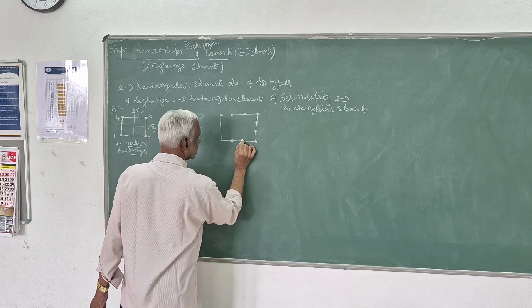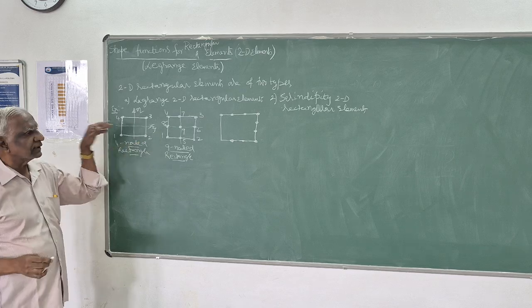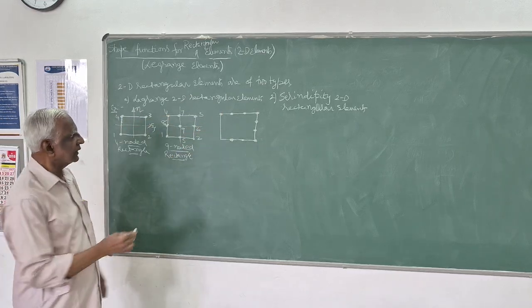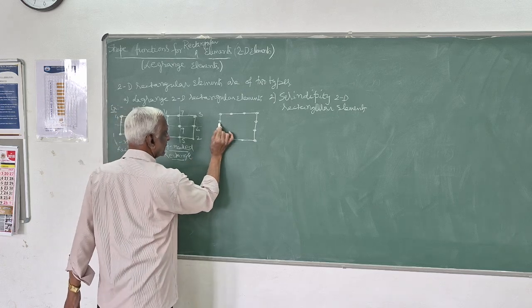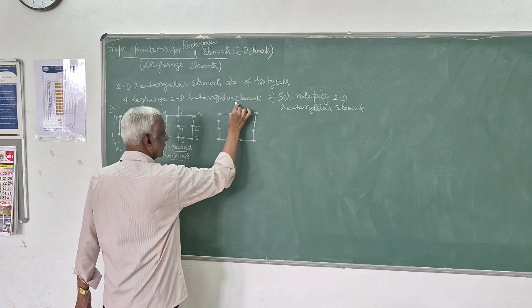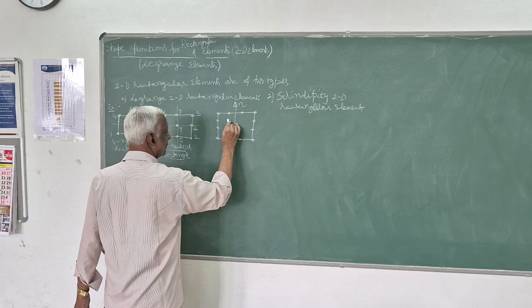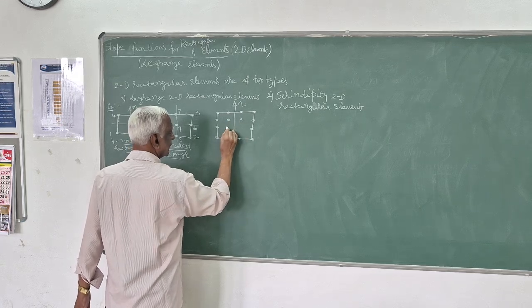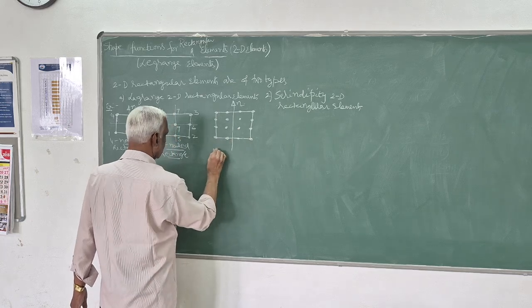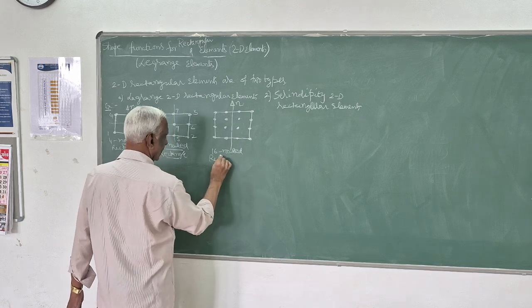In the line element you saw, your nodes lie on the edges, then in the middle, and 2 in the line. Same thing in the 2-dimensional rectangular elements. Also, if the nodes are distributed like that, it is a 16 nodal rectangle.